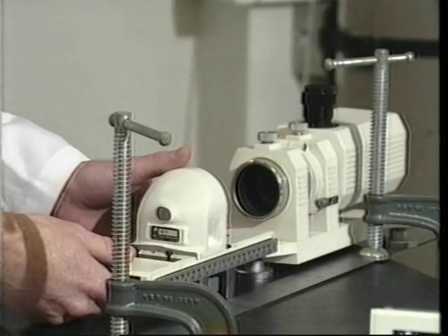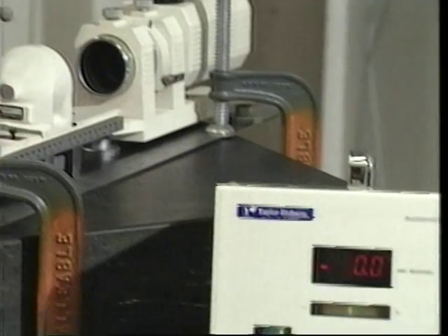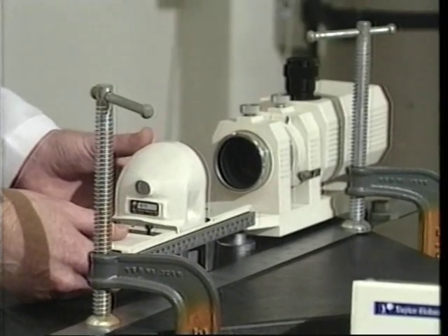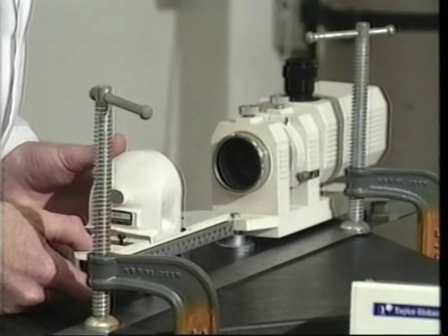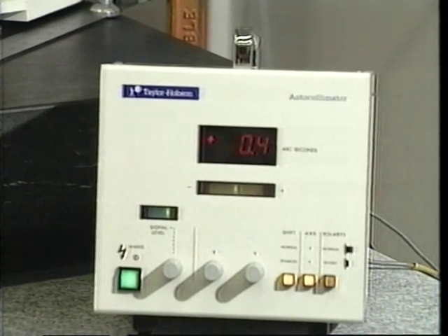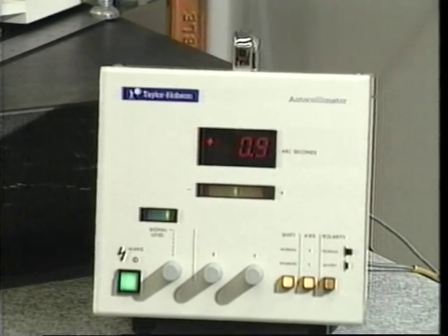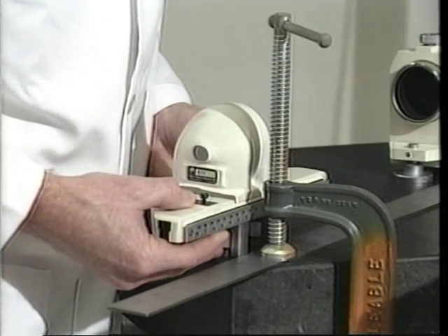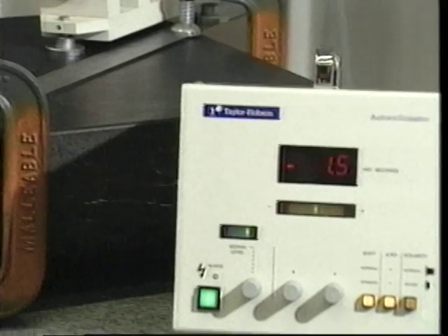With the reflector at the first measurement position and the display zeroed, the first reading of 0 is recorded. The reflector sled is carefully moved to the second measurement position. The second reading is recorded. This procedure is continued until all the measurement positions have been measured and recorded. Increased accuracy can be obtained by measuring and recording the angles at the measurement positions in reverse order, then averaging the values from the 2 procedures.